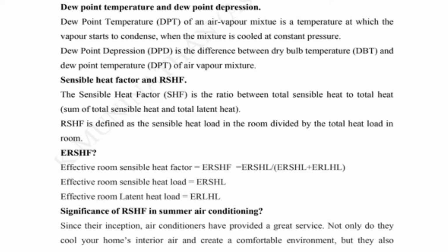Then sensible heat factor and RSHF. The sensible heat factor is the ratio between total sensible heat to the sum of total sensible heat and total latent heat. RSHF is defined as the sensible heat load in the room divided by the total heat load in the room.